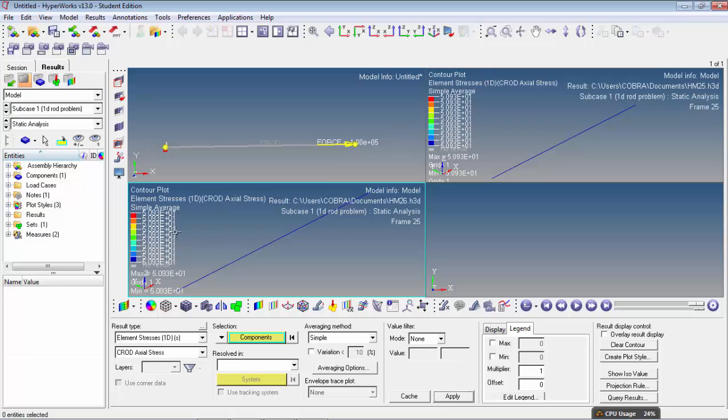So when I compare this one, there is no effect, because the rod element only supports compression and tension. So if you are using the rod element, then you have to constrain the nodes in the loading directions.